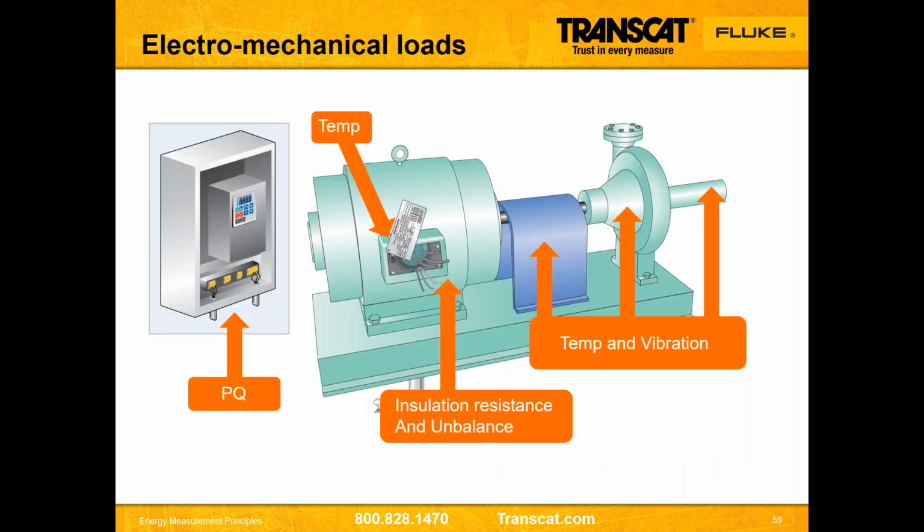In electromechanical loads, lots of things we can go look at. Obviously, not just the power quality feeding the load, is the quality of the voltage good enough to support the load? Well, what's the operating temperature of the device? What's the actual health of the insulation, which we would do with something like an insulation tester? How balanced or unbalanced is that load from a standpoint of voltage and current? What's the operating temperature of it compared to the nameplate? What's the vibration of that mechanical load look like?